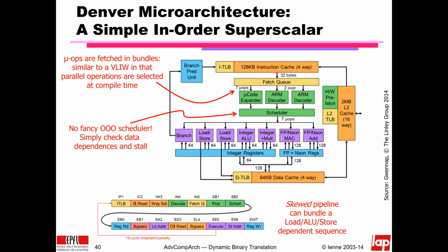So you can read this processor as 2 completely different paths and processor: the one made by these 2 decoders and the rest, which is a simple, not particularly good probably, but semi-decent in-order superscalar, and the processor that is done by this microcode expander and again everything else, which is a pure sort of simple VLIW, right?